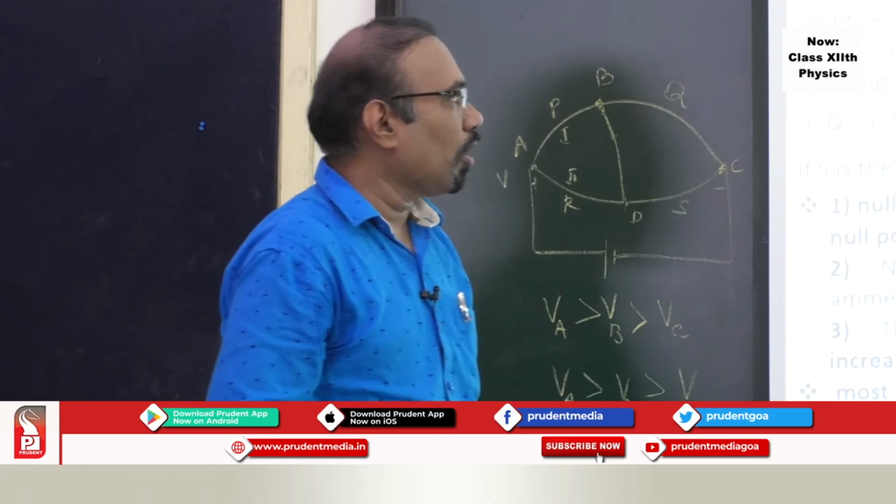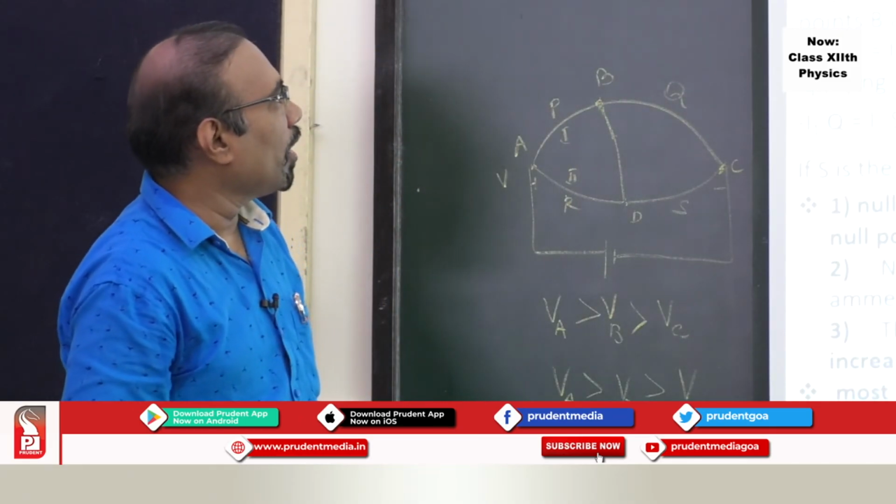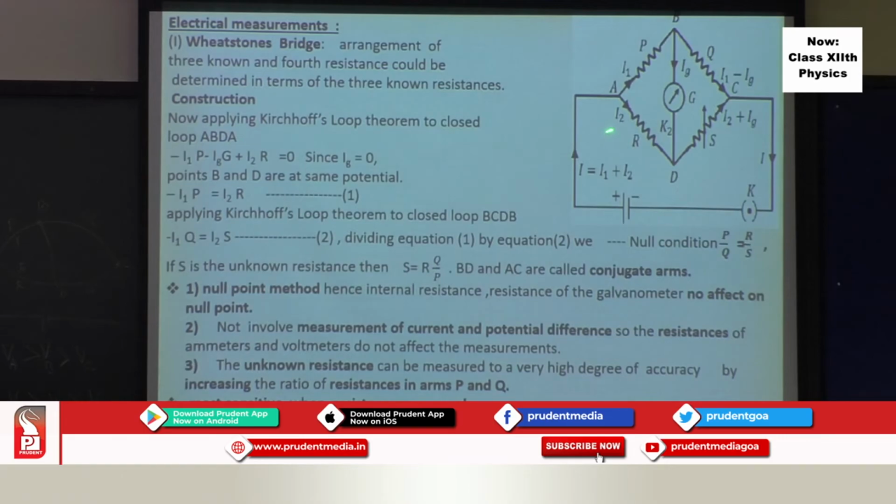These arms are called conjugate arms, and this is what is called the null point method. So internal resistance here doesn't matter. There is no involvement of measurement of current and potential difference across the resistance, and the galvanometer's resistance is not taken into account. It's more sensitive when the resistances P, Q, R, S are of the same order, and if there are very low resistances or very high resistances, it's not so suitable to use this Wheatstone bridge. So you can find unknown resistance in terms of 3 known resistances.